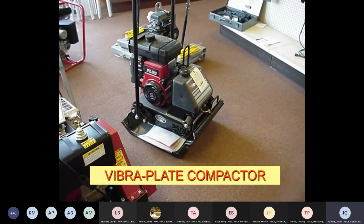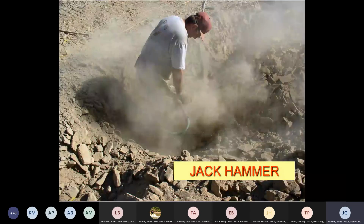Vibratory plate compactor. These compactors only weigh a few hundred pounds, and we don't want to install lifts more than 2 to 3 inches when we're compacting with these compactors. They just do small areas. Jackhammer. Try not to get these on our sites, just because they're very labor intensive and can be dangerous to use.